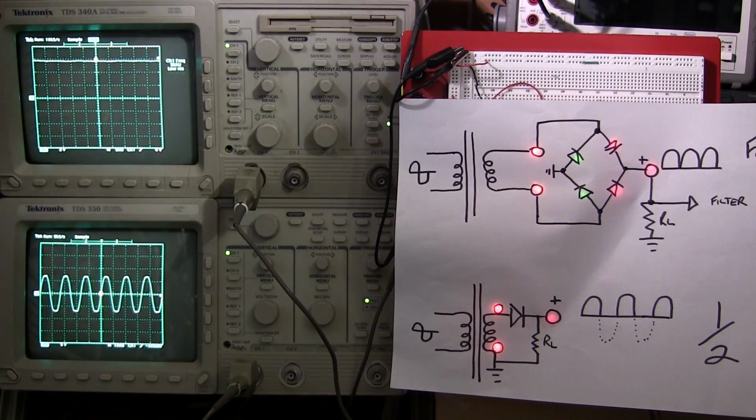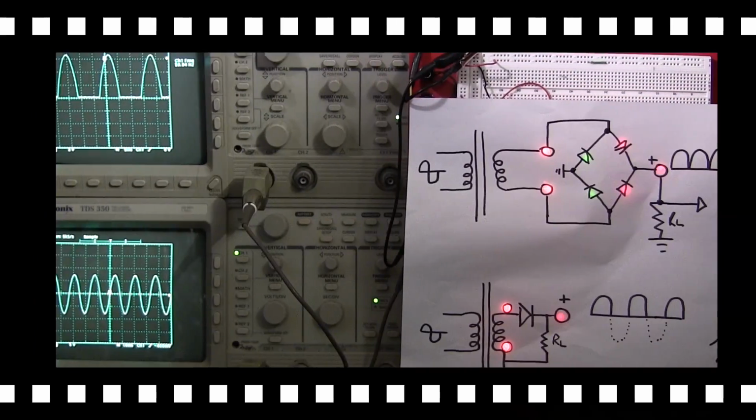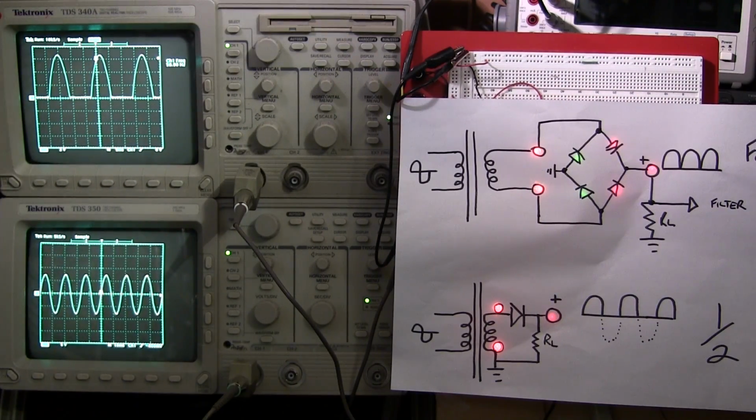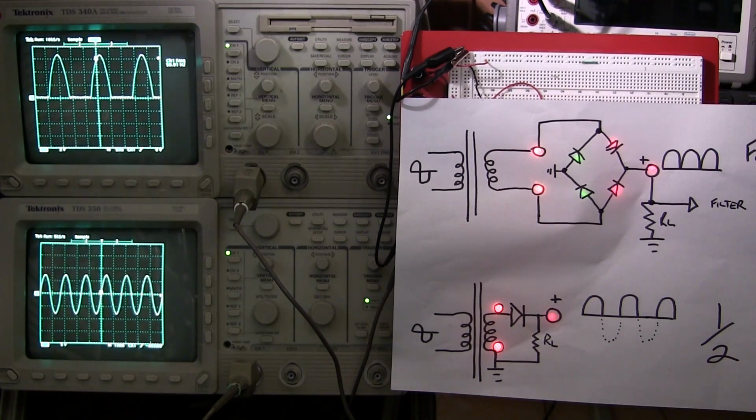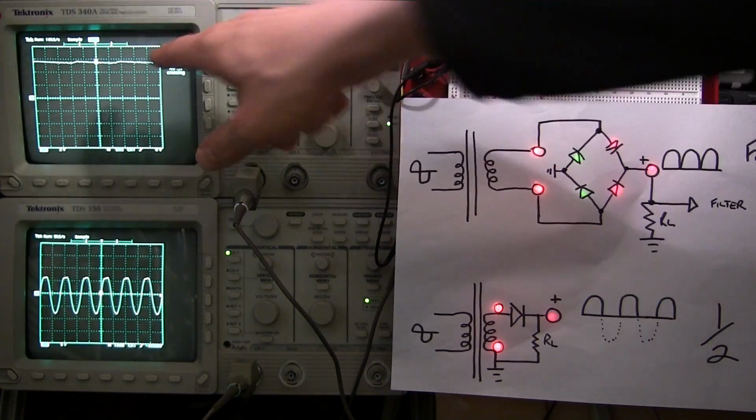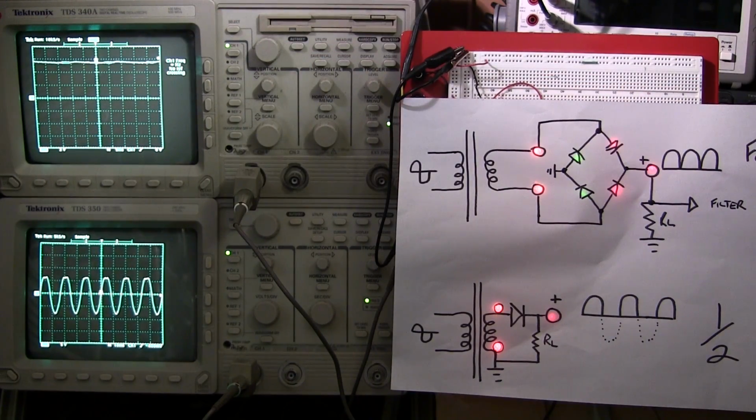So now what I'll do is switch the probes around to the half-wave rectification circuit, and we'll check that one out. All right, I've got half-wave rectification hooked back up here again. And what I'll do is hook a filter capacitor in line with this. Same value there. And you can see we still have ripple with this. You can see that ripple kind of moving across here. So I'll load it just a little bit more, and we should get just a little bit more ripple out of it, indicating that we need a much larger capacitor. You can see how it's coming down there.